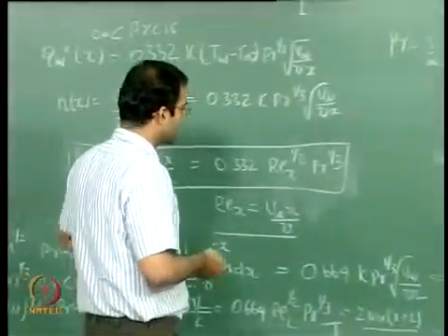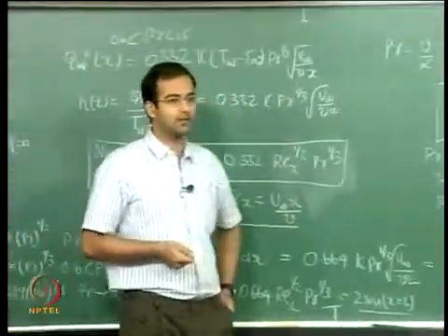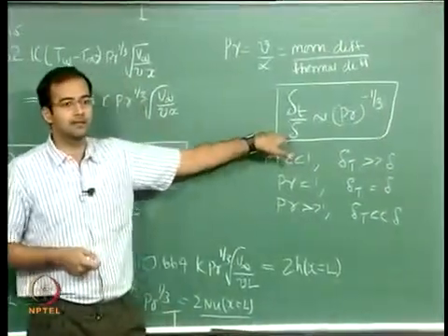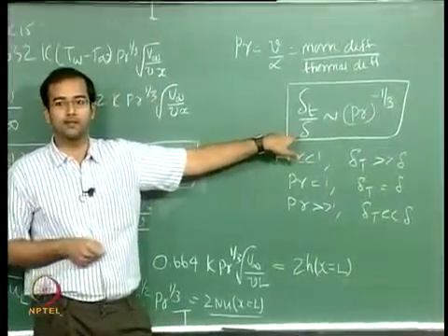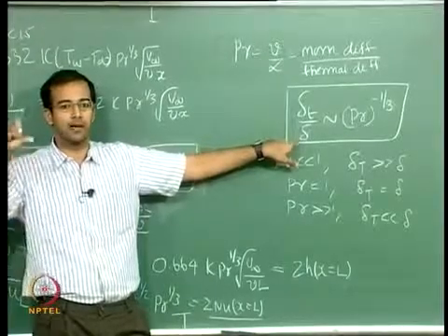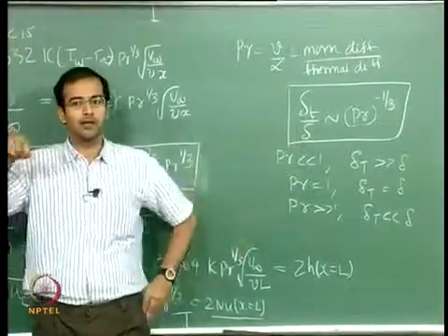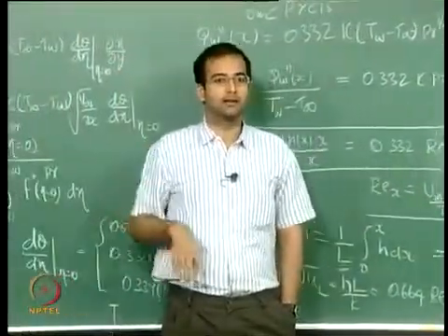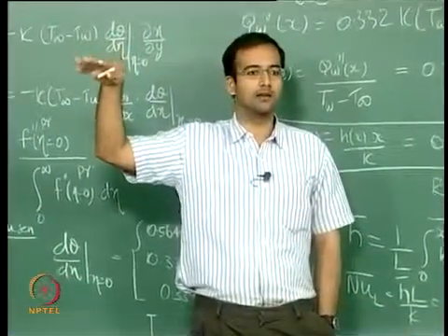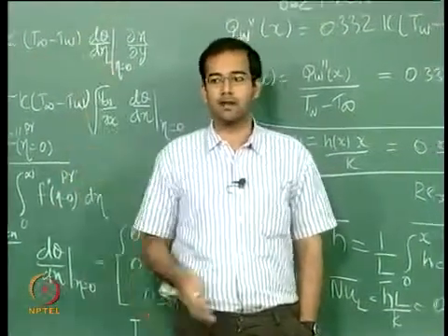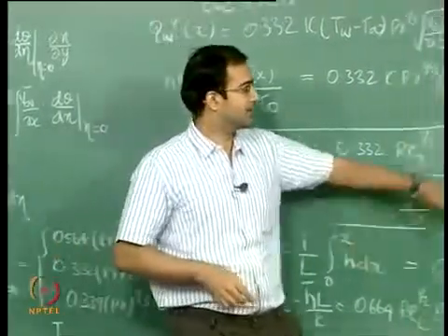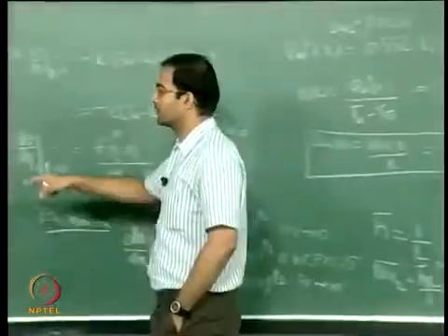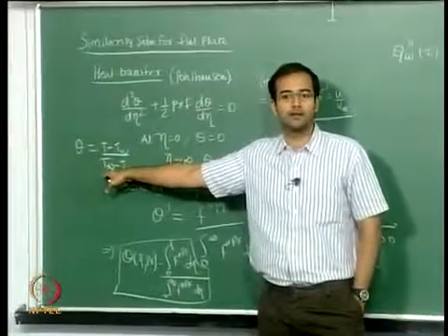Okay, so in fact this will also be a very nice exercise which I can give you in your homework. You can calculate the thermal boundary layer thickness once you get your Blasius profile, right. So that is the value of y corresponding to the eta where your u by u infinity goes to 1 or 0.99, or f prime that you calculate should be approaching 0.99. The corresponding value of y will be delta. The same way thermal boundary layer thickness is defined as the point where your theta goes to 0.99, okay, the corresponding value of y.